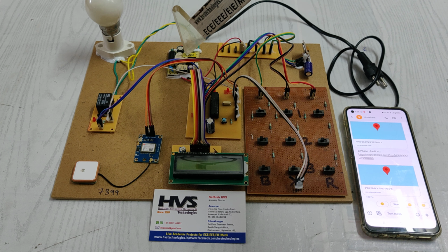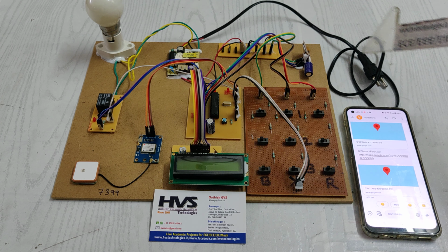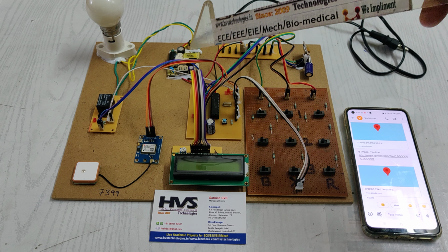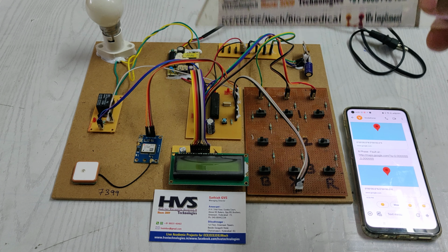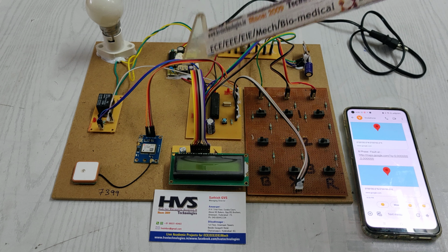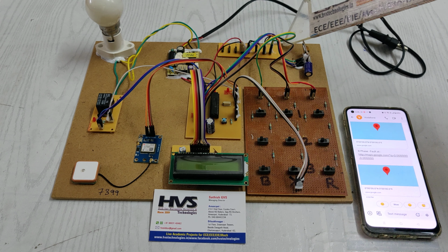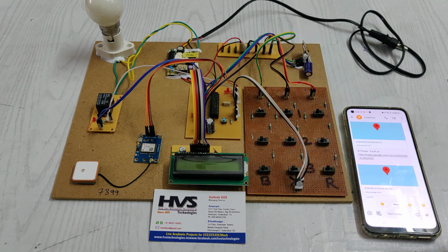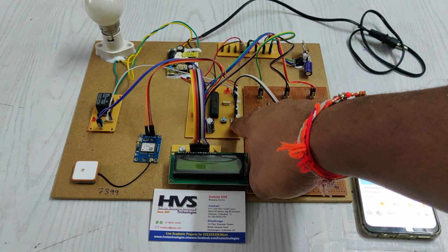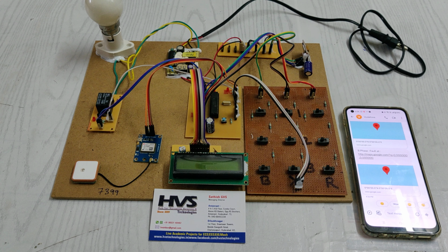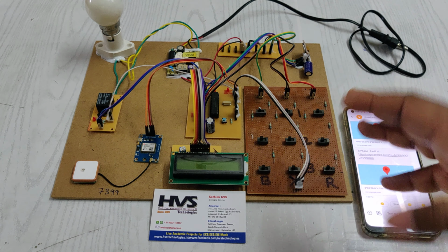This is a regulated power supply board which takes 230 volts AC input and provides a 5 volts DC output, as it has 4 stages: transformation, rectification, filtration and regulation. After the 5 volts is input to this breadboard, from there we distribute the 5 volts throughout the input and output modules of our project. Coming to this motherboard, the blue color switch is the reset switch, which plays a major role in our project during execution.